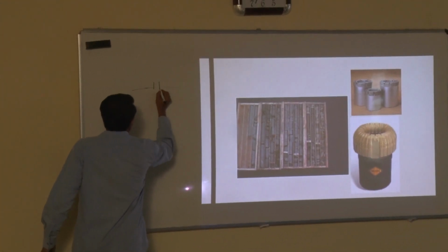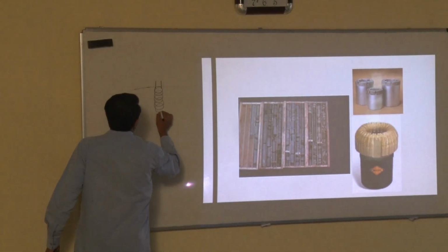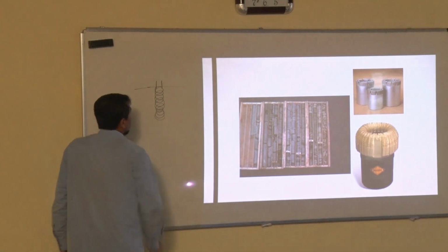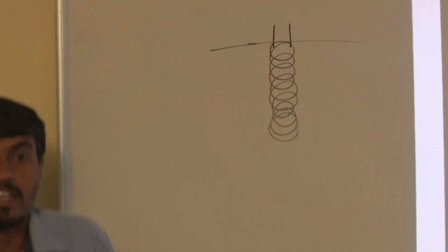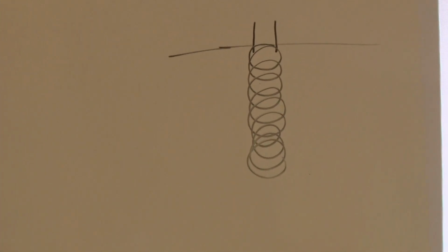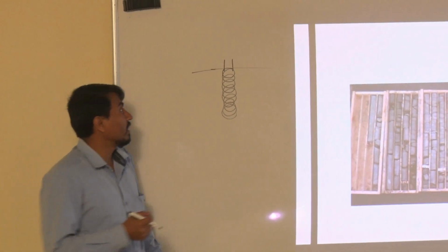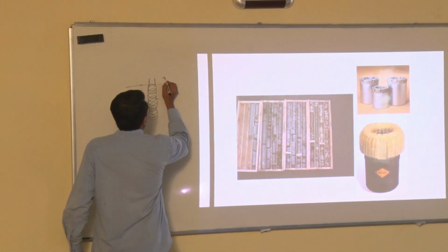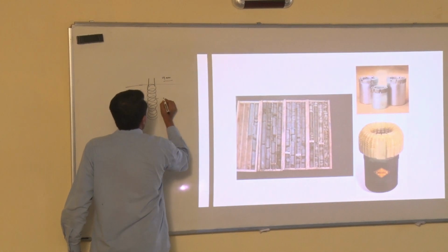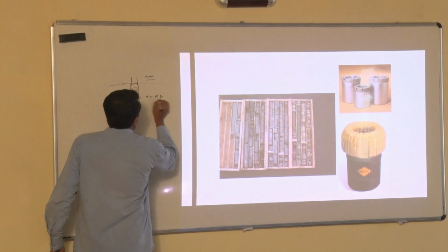When the drill is running, suddenly when there is a discontinuity, the driller will experience a higher rate of advancement of the drill rod. So an experienced driller takes note at that particular time, suppose they started at 9 am and at 9:11:56 they observe this.